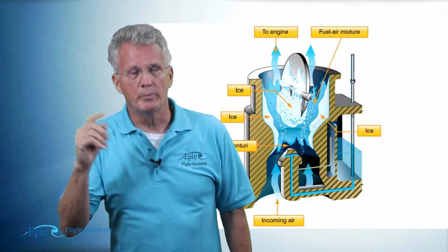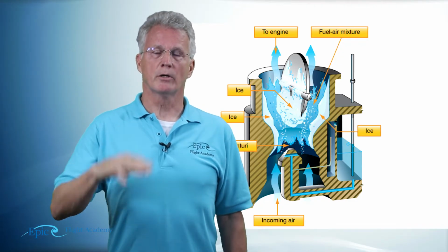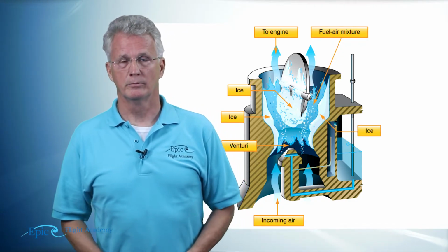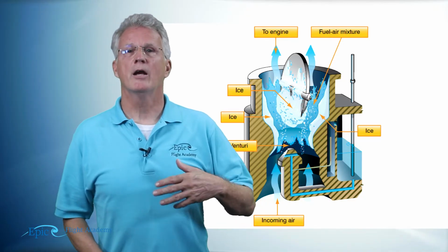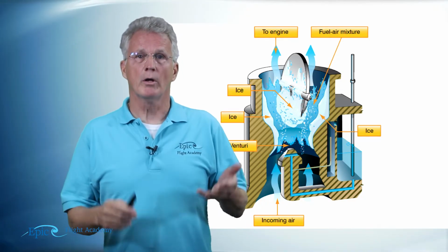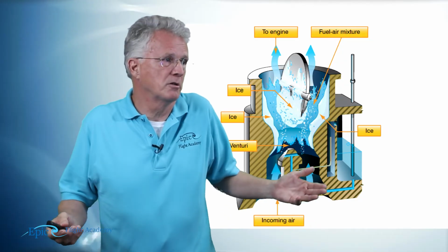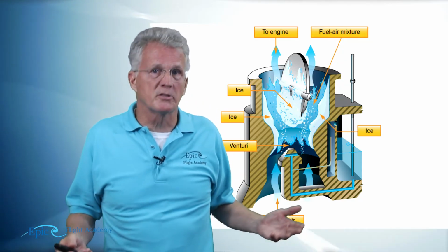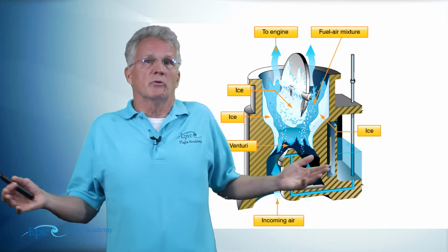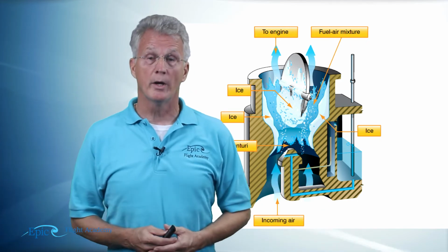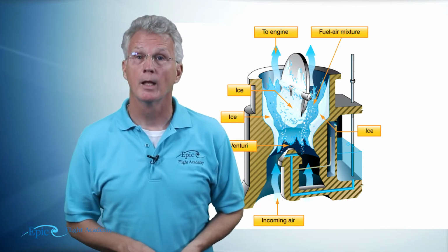What we may fail to remember is we take this aircraft up in altitude. The air is cooler because we've gone up in altitude. Well, what if the air is still, maybe I go up 6,000, 7,000, 8,000 feet and the air is still 50? It's still a long ways from freezing.